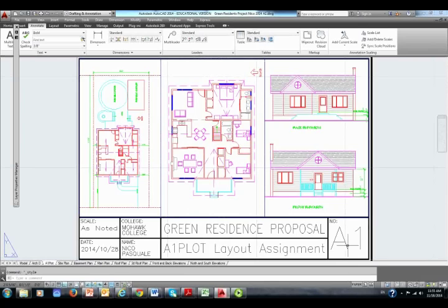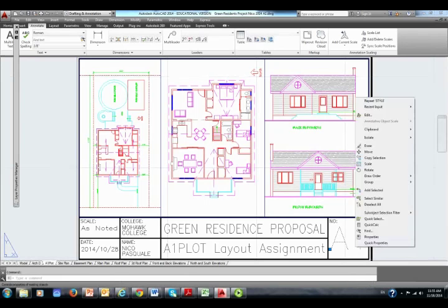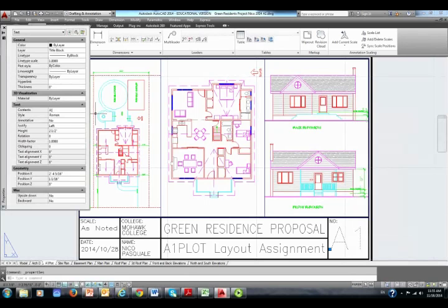So what I could do is simply click in paper space my number, and a couple things will happen because Nico didn't use fit. Different font will stretch differently. So we'll do 2 things. We will go to right-click Properties, and we'll change, just so you see why the fit is so good to use. We'll change it to bold. Well, we got lucky, but it should also be fit.